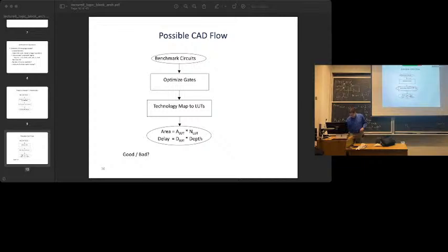And then my delay, well, I've got the delay of one LUT. I'll get that by doing my transistor level design and spicing it. And then I'll take the depth. So that's the most number of lookup tables that are in series in my design. So maybe in this case, the most lookup tables in series between flip-flops is 2. That would mean my depth equals 2. Okay? So I can get the depth and I can get the number of LUTs after synthesis, right?